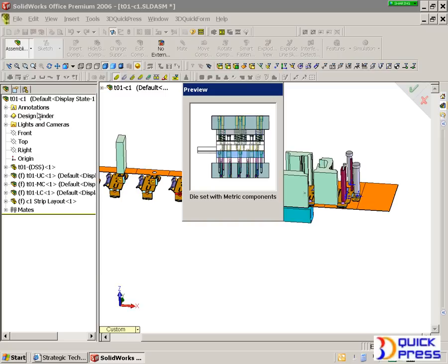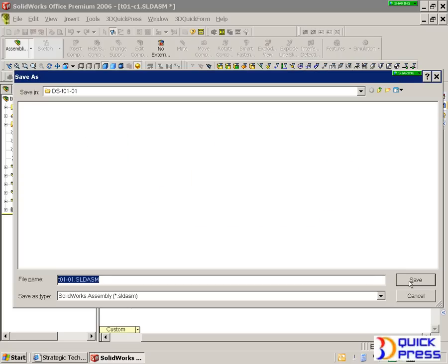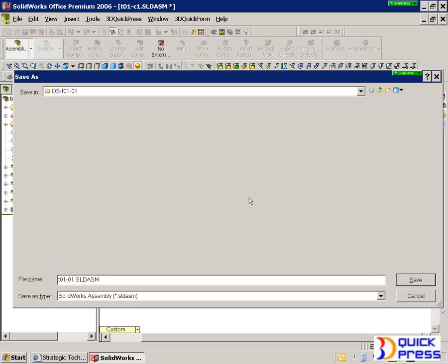So we have an option. Do you want to create all the holes in the die set at once, like when I build the die set? Because there's a lot of other things going on here too. We have to size the die set. It has to pick up on any thickness variations, penetration depth, all the variables we've kind of set so far. Then it's got to look through and it says, hey, what punches are interfering with what components?